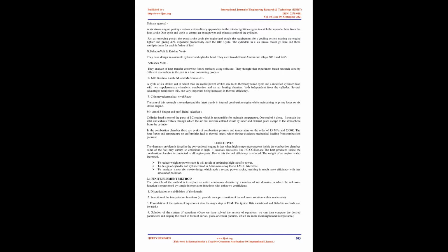As shown in the component weight ratio of the materials: steel is 53% for the weight-reduced engine and 86% in the base engine; cast iron 33%, 13%; aluminum alloys 7%, 1%; plastics and elastomers 6%, 0%; other lightweight materials such as titanium alloys and magnesium alloy 1%, 0%; ceramics.